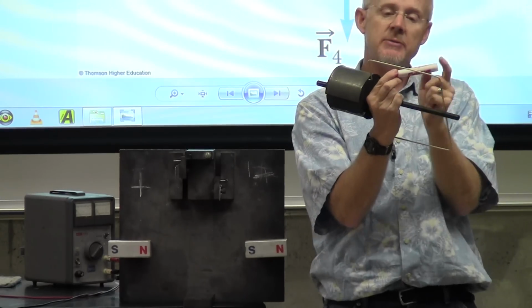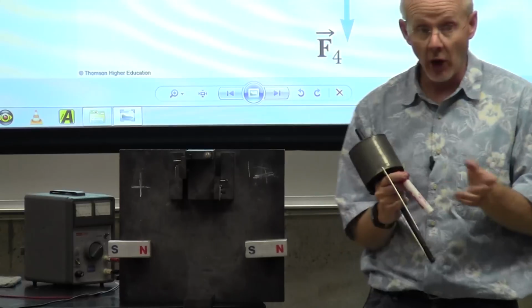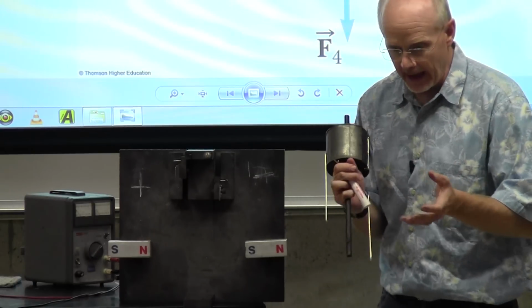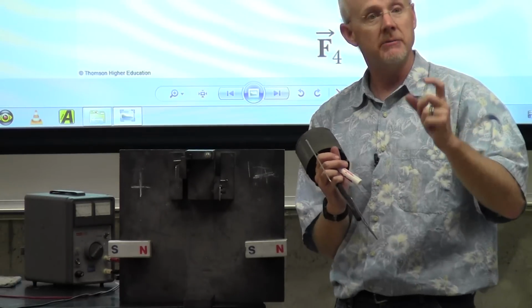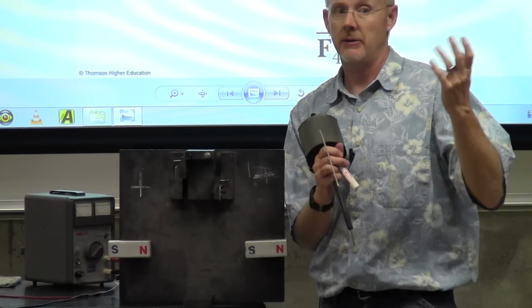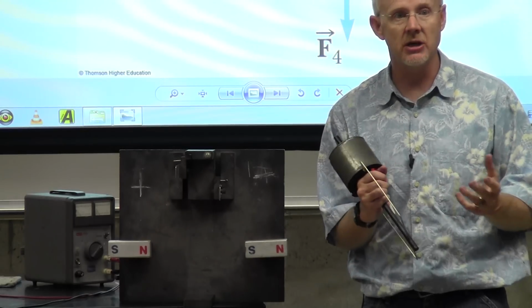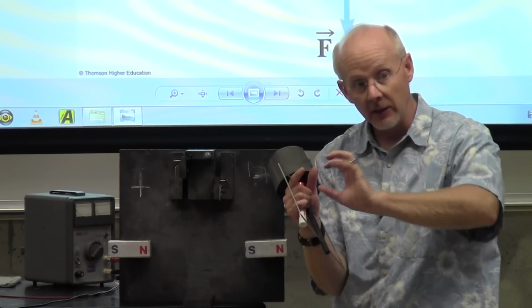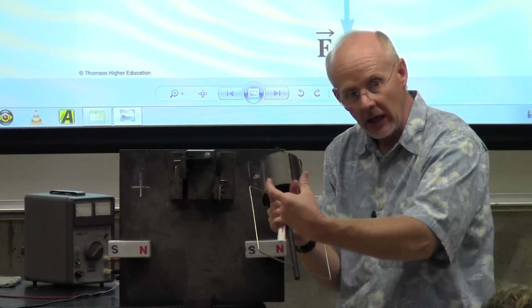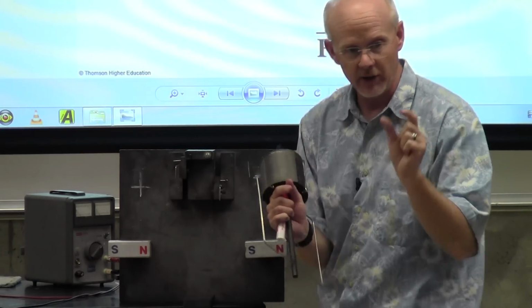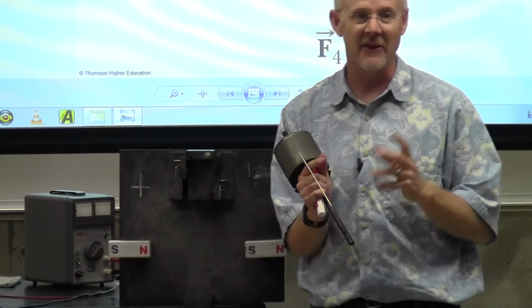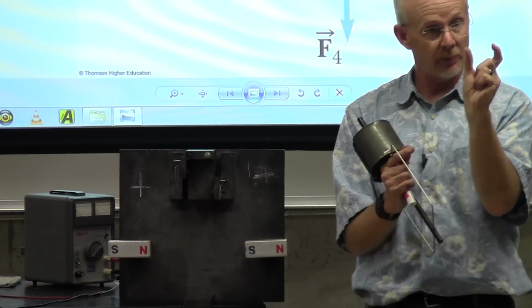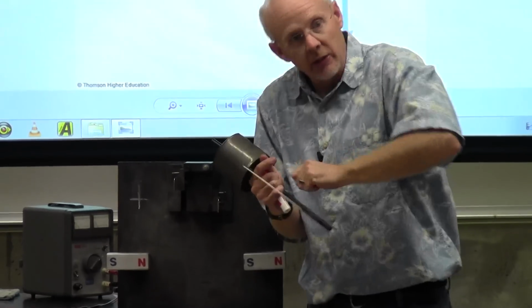Now eventually, these brushings are going to wear out. I know that my table saw has replacement brushings, and it seems like every 6 years I've got to go down and go under the table saw, and it has a little screw hole. You pull it out, you pull out the spring, and at that point there's just a hair of graphite left, and then you go down to the store, and you get a new piece of graphite with a spring, and you reload it, and tighten it in, and keep going.